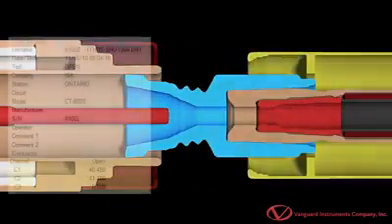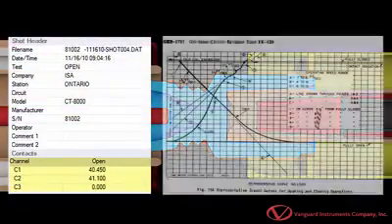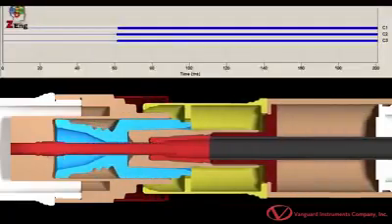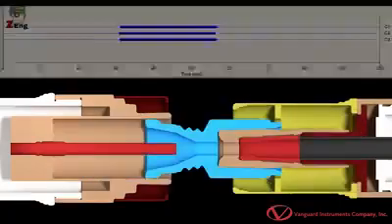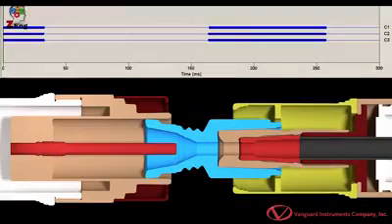Contact timing tests are used to compare the breaker's main and resistor contact performance against the manufacturer's specifications. The breaker's open, close, close-open, and open-close-open operations are timed in milliseconds and cycles and compared with the manufacturer's specifications to determine the performance of the breaker.